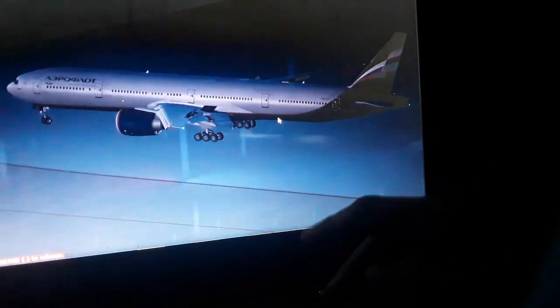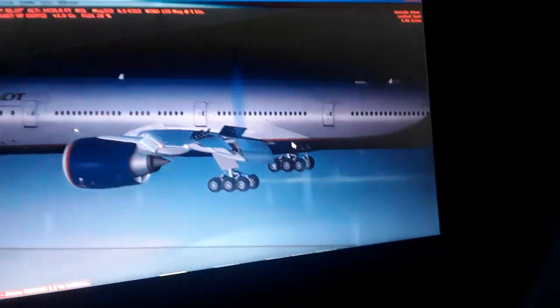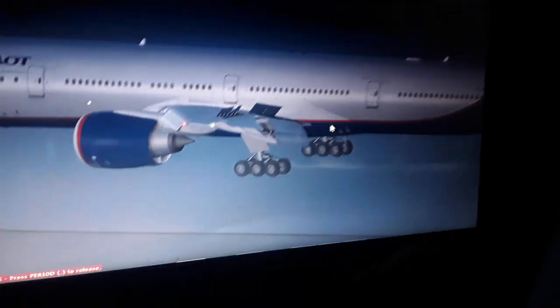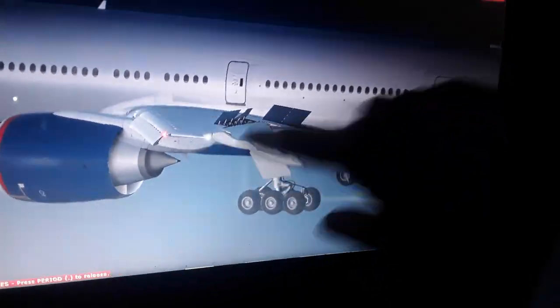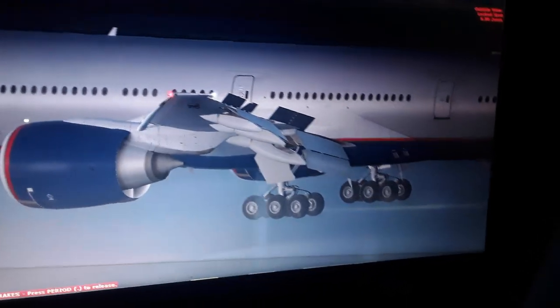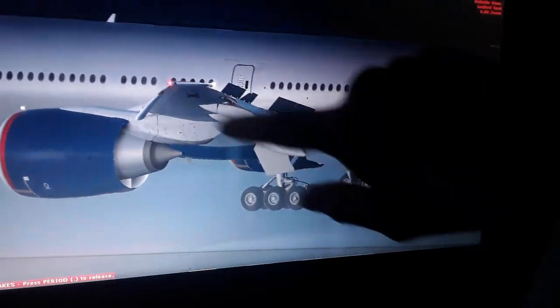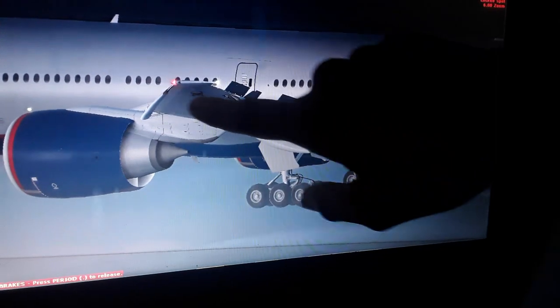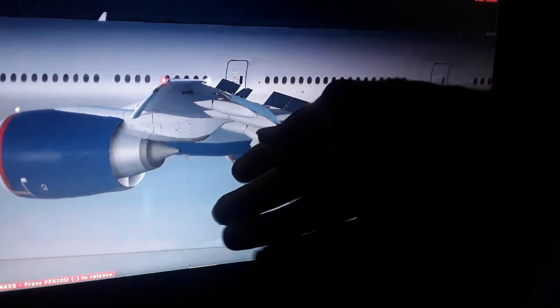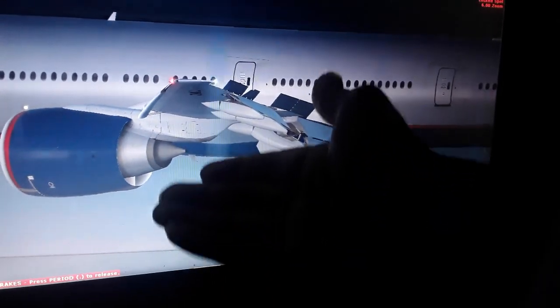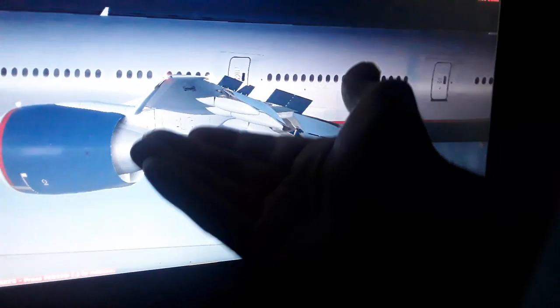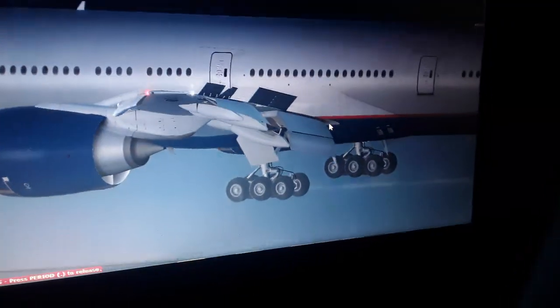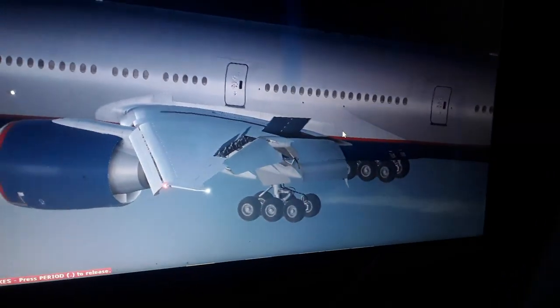We have also, you can see here, the bottom surface of the wings. The surface is more flat, so the airflow of the air mass as the aircraft accelerates for flight is moving slower. Using the Bernoulli theory of fluids, we have higher air pressure below the wings, which pressurizes the aircraft and lifts the weight up into the air.